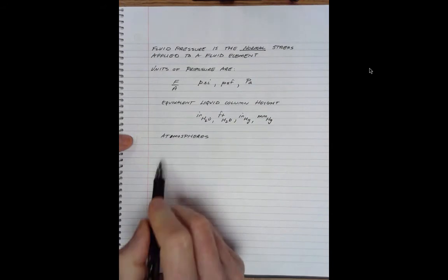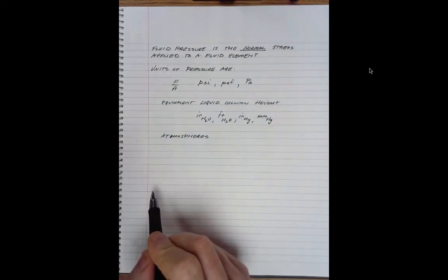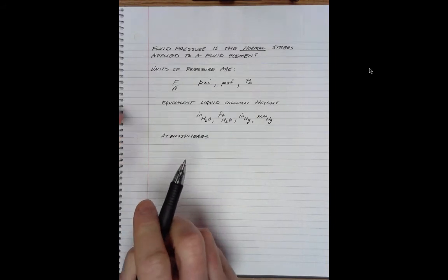Spelling there. And this is the ratio of the measured pressure to 1 atmosphere, usually at standard surface conditions. For instance, in the case of air at 59 degrees Fahrenheit, standard atmosphere is 14.7 pounds per square inch, 29.92 inches of mercury, 101.325, I think that's kilopascals, and so on. So there's lots of units of pressure. They're all three used quite a bit, and sometimes interchangeably. It's obviously problem contextual, but they're all conveying the same information.